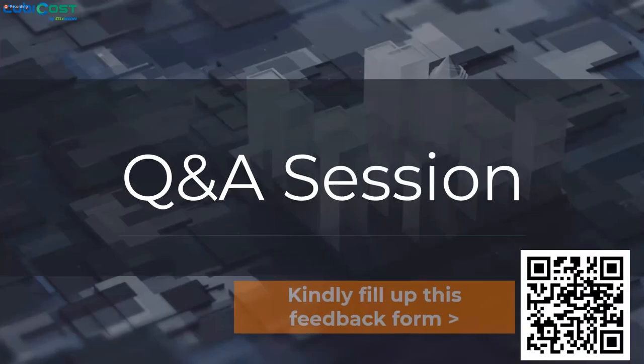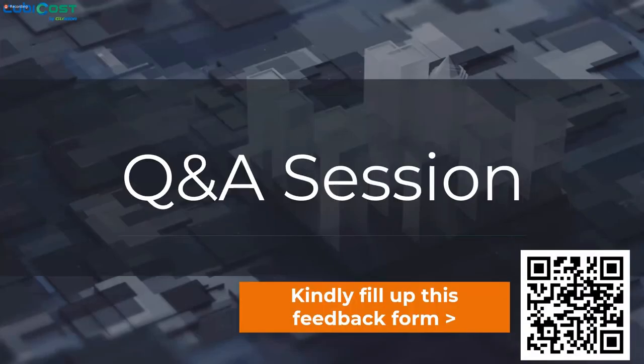Okay, now we'll proceed to the Q&A session. The first question is from Wong Xiu Ying: if we input additional vertical bar in both calculation rules and attribute editor, will the quantity be duplicated or will the attribute editor take precedence? The answer is yes, it will be duplicated. One of the scenarios I can share where you would really require this additional vertical bar in attribute editor is this.